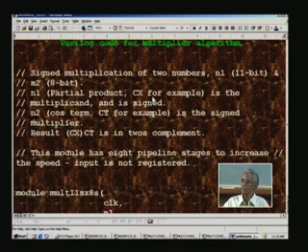In DCTQ we are basically evaluating a cosine transform, and for that we need some cost terms. These are all stored in a ROM table, the design of which we have already seen in the ROM design. We also mentioned that it was with this end goal in mind that we took all these examples such as ROM, RAM, dual RAM, the adder, and the multiplier we are now looking into. All these applications are aimed at DCTQ, which is used for video compression in JPEG and MPEG.